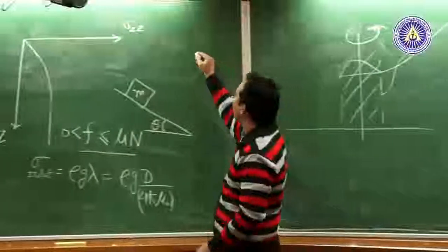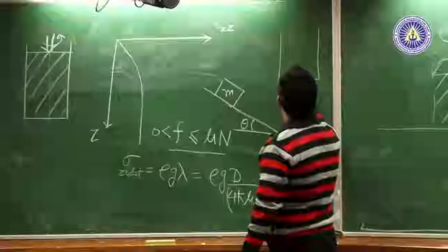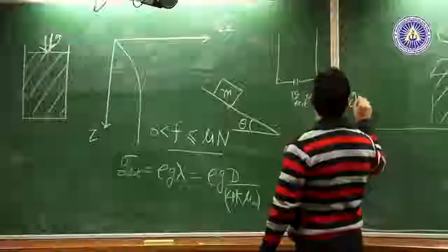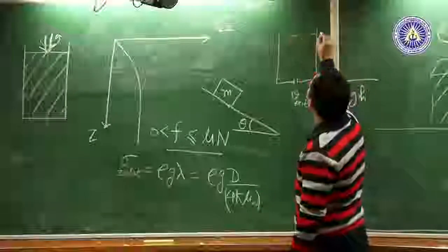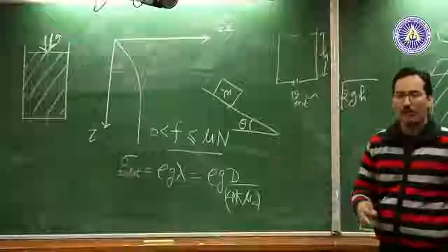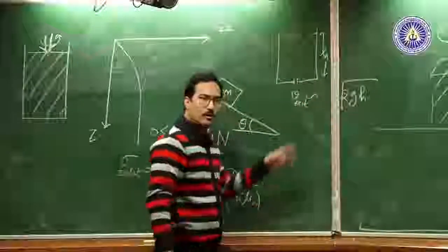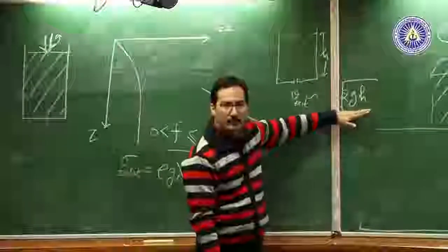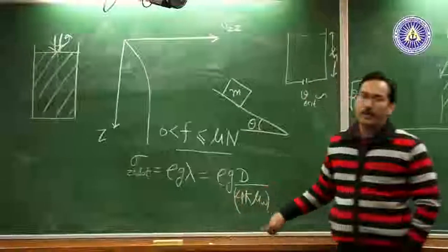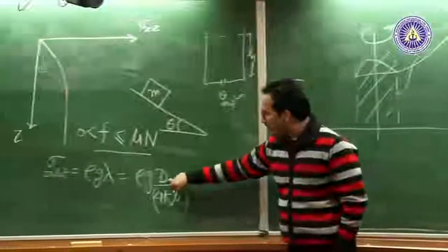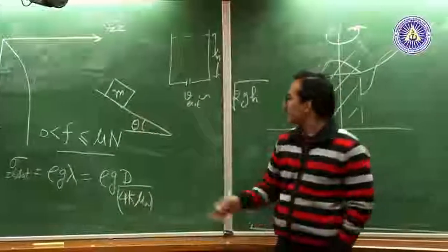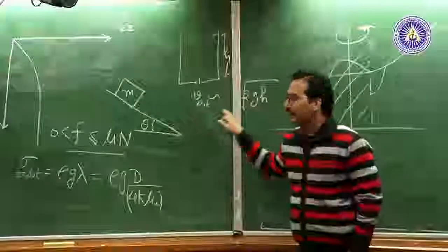So in a fluid, if you had a fluid container, you say that your exit velocity goes as root 2gh because your pressure variation is hydrostatic, right? And so the pressure here is hydrostatic if you really want to apply Bernoulli, like half rho v squared plus rho g h, and you get this kind of velocity scale. For this case, when your pressure is saturating, you would like to apply a similar relation, except that your pressure is no longer hydrostatic, it's some constant, and since pressure is independent of height, you would expect that.